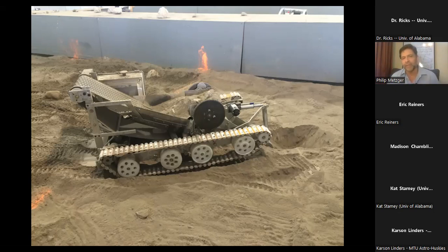And so we asked Eric and the others at CAT, and they said, well, for one thing, it's a lot of iron or steel and a lot of horsepower. And so that dust and dirt can get pulled right into the wheels and crushed to powder and then extruded. So if you have a big enough vehicle with enough power, you can just power through it. But on a small vehicle like this, that's not really an option. And so that's partly why it's so hard. But even so, Caterpillar told us that their tread systems are very highly engineered systems of systems. There's a lot to it.